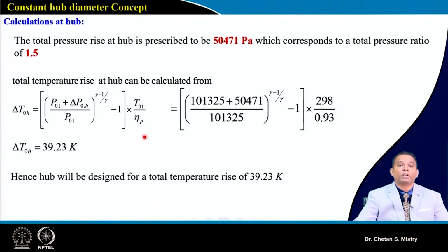It may be possible, like we have discussed earlier, that some portion near the hub region of this compressor may act like a turbine if we are not designing properly, and that will lead to losses, maybe in the sense of pressure rise or in my operating range. That's the reason we need to select this number iteratively. In order to have that flexibility, we now have our Excel sheet program with which we can do the modification we are looking for.